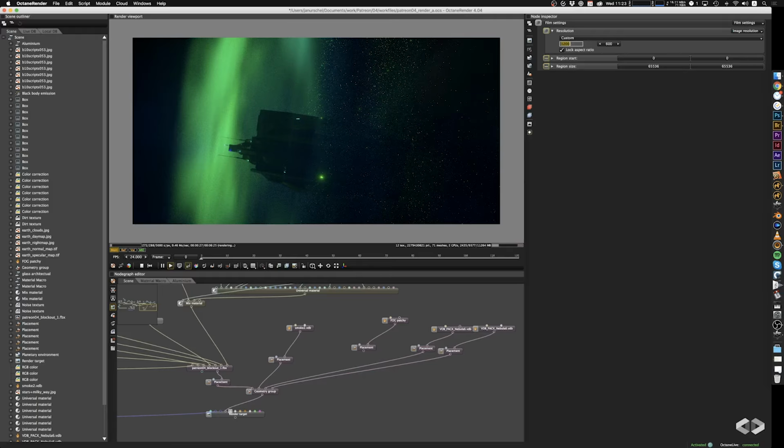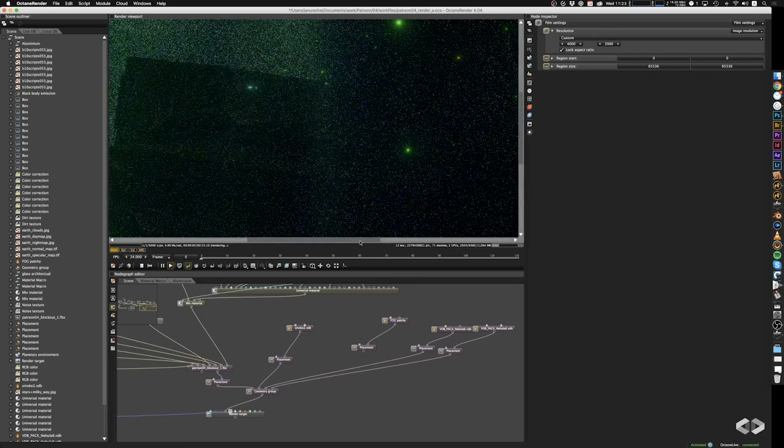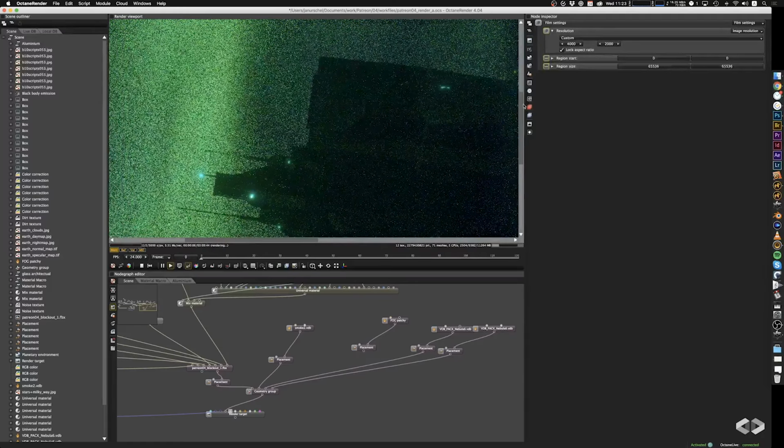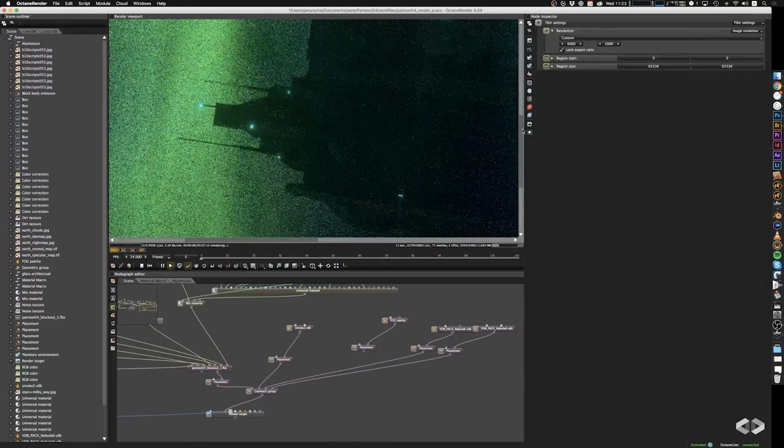The volume will give me just the volume pass, and I can add or mix my volumes more accurately and more distinctively in Photoshop. And the material ID pass is for me to isolate the object from its background, and also to select certain parts on my ship should I need it.